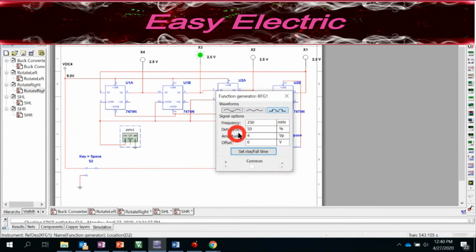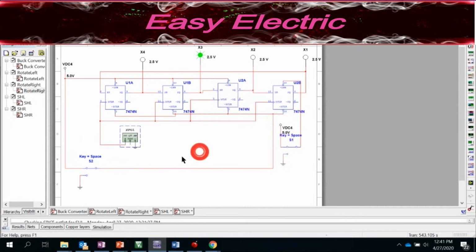What's the frequency of your clock pulse? It is actually 0.25 hertz. Okay. So the preset, these three presets connect to 1. In our design, we connect this to 1, 2. The reason I connect the last preset to the switch is that I want to be able to produce just one, then see the movement of that one inside this